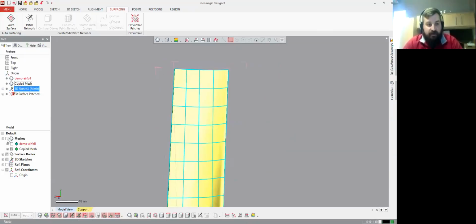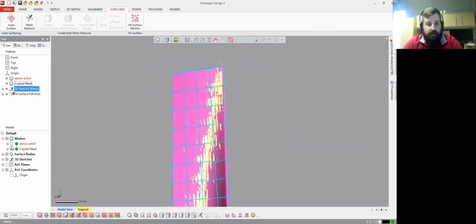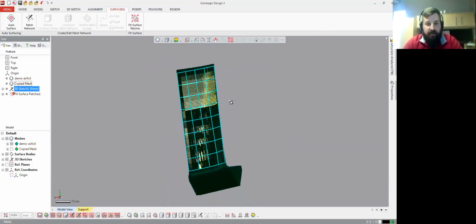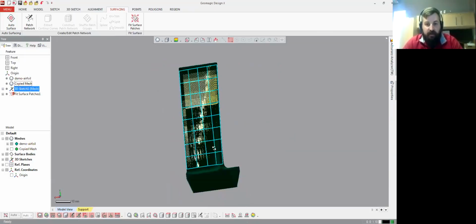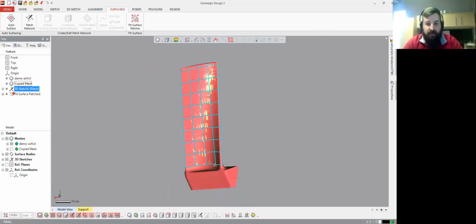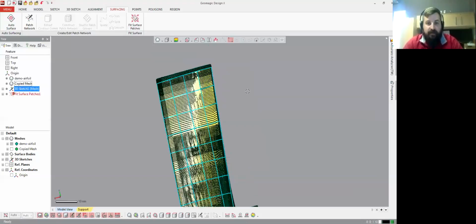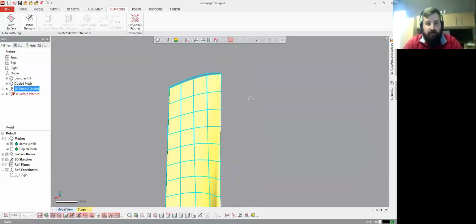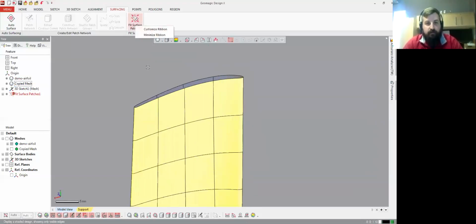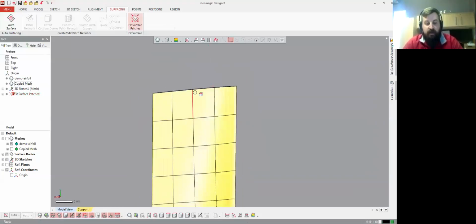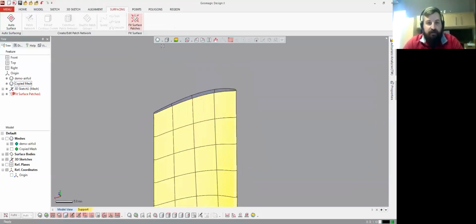So the next thing I want to do, now that I have that blade, is solidify it by extending it and capping off the ends. That allows it to merge with the body that we're going to create down here using traditional mesh sketches. First, I'm going to extend everything and make sure that we're going past the areas that we need so we can trim those off later.